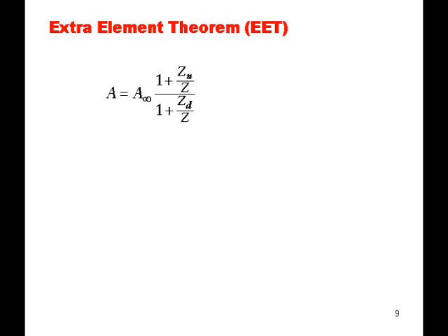And that's particularly useful if you designate a capacitance as an extra element. Because if the rest of the circuit is all resistive, then those two driving point impedances are also driving point resistances, and the Z is an S term, a reactance, and so the formula gives you the pole and the zero caused by that capacitor right off. In other words, the formula itself is a low entropy expression. You can see where the terms come from. You know what you have to change if you don't like the answer.